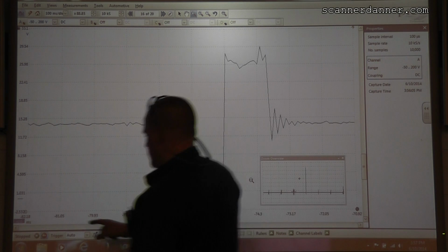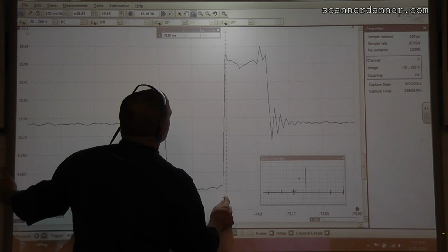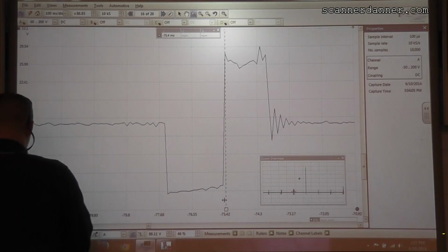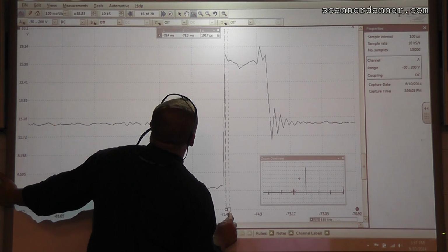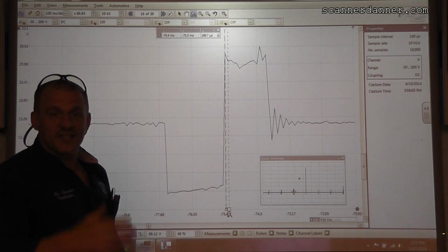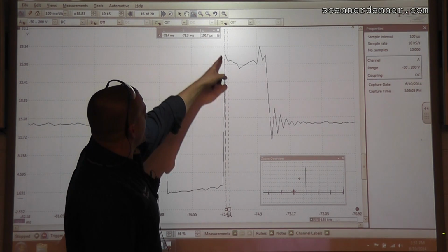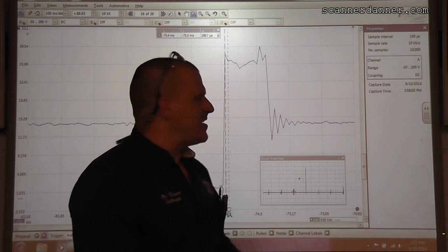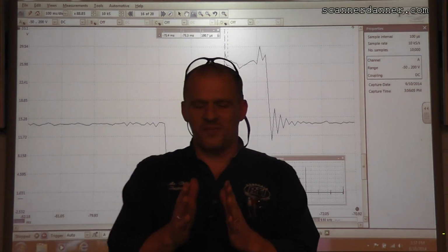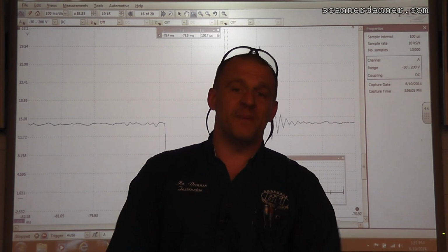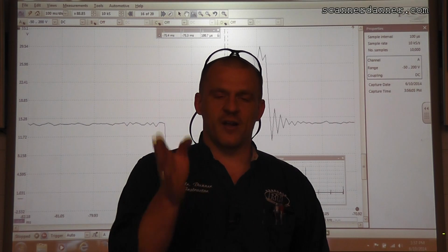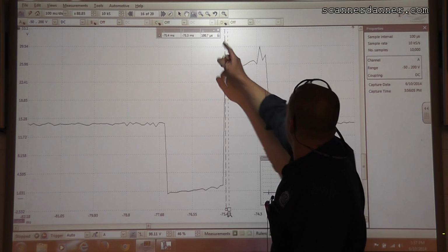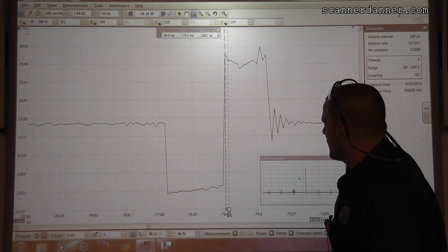I wonder if I can, just want to try something here. I'm pretty sure I have a sample there. And I'm pretty sure I have a sample there. Yeah, check it out. You can actually see the sample, 100 microseconds. So I put it at the point there, and I put it right there. So listen, what you need to understand is if there's an event going on between these two cursors right now, I'm going to miss it because my sample interval is too wide. That's 100 microseconds right there, delta time. 100 microsecond interval. That's pretty cool.